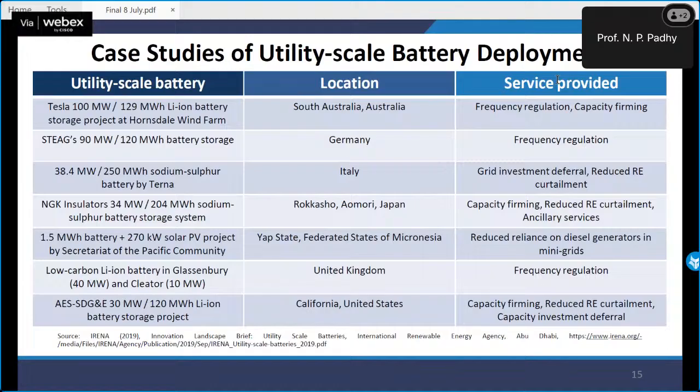But it is also possible that I can have a 100 megawatt battery, am I right? But the total capacity of 200 megawatt hour, that means I have a battery bank, discharging at first hour 100 megawatt and second hour another 100 megawatt. So my capacity is 100 megawatt at a given hour, but the total capacity is 200 megawatt hour.